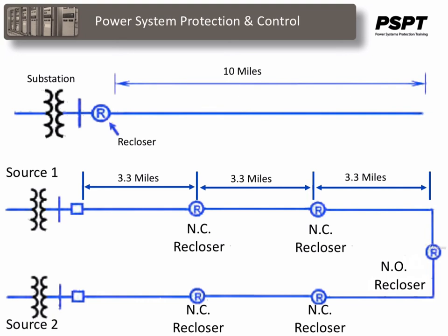urban areas. These points of connection allow various configurations by the operating utility by closing and opening of switches along the feeders. Operation of these switches may be by remote control from a control center or by a lineman or crew sent out to do the switching. The benefit of the network model is that in the event of a fault or required maintenance, a small area of network can be isolated and the remainder can be kept in service.